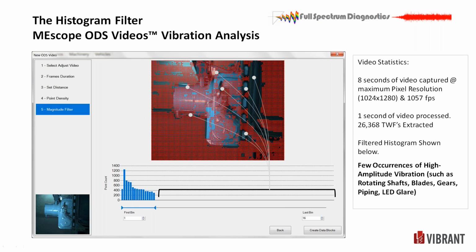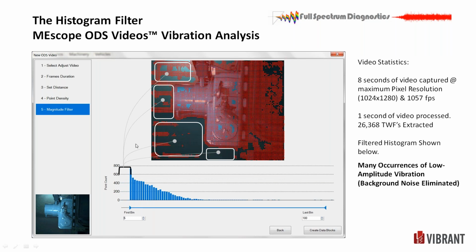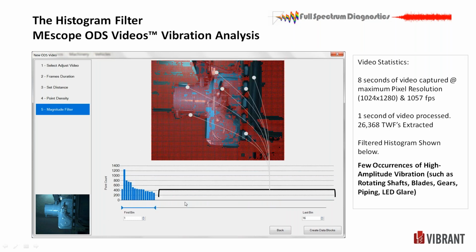It's going to extrapolate from there and give us a smooth response of what the whole structure is doing. But in order to get rid of all this noise back here, based on the second thing, we'd have to really eliminate a lot of these peaks, and you start losing some of the data inside. So there's a happy medium in there somewhere. And if you play around with it enough, you'll get an idea. You can always go back and refilter.